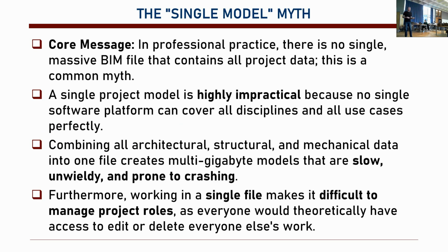And one of the myths is that to have a single model, okay? So people think that, well, we will have a single model where people will be adding, removing things, but that's not the way it works. Okay, so this is basically a myth. Okay, so we cannot have a massive single large BIM model that can include everything. Okay, so for that, because it's impractical. Okay, because there is no software that can handle that much of data and run fluently.